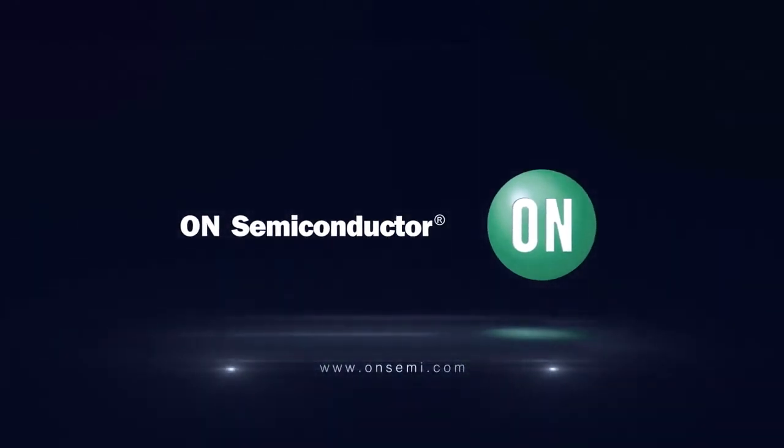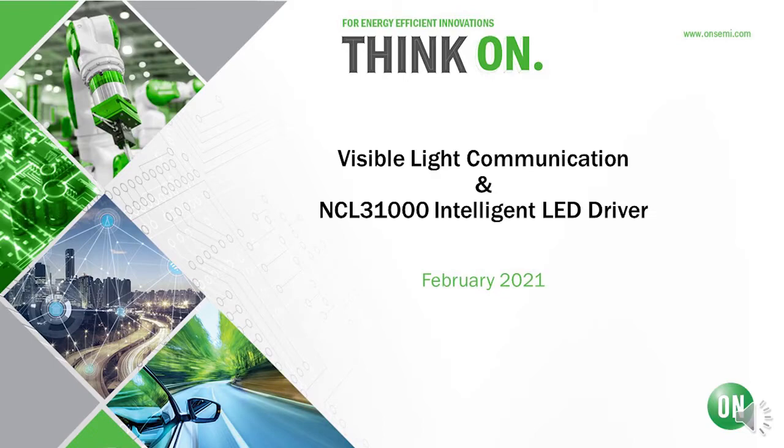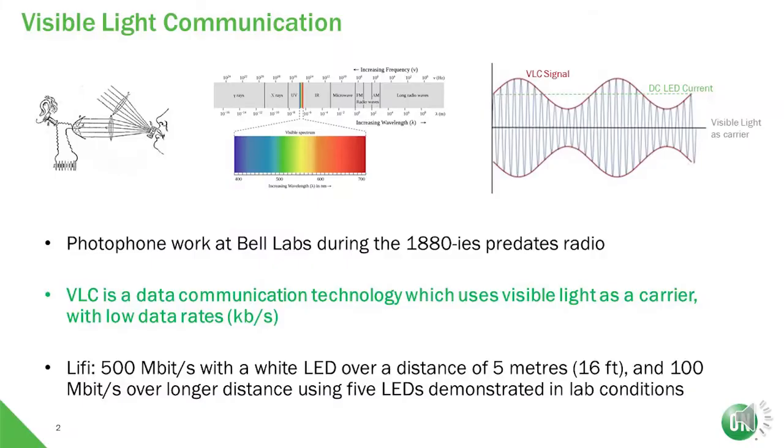Hi, in this instruction video we will briefly cover the NCL31000 intelligent LED driver and visible light communication. Visible light communication is an optical communication method that works inside the visible spectrum. You can think of it as a simple amplitude modulation where the visible light is the carrier and the information signal is modulated on top of that.